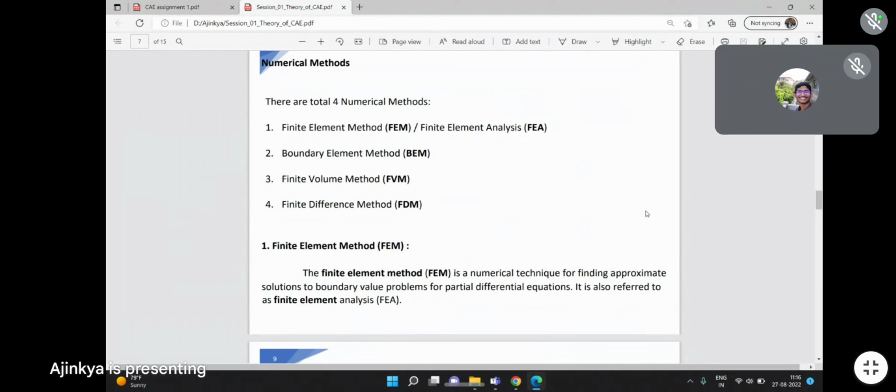What my equation of motion tells me, maybe I'll just write it for you. Force is equal to mass into acceleration, plus k into x, meaning my stiffness into my deflection, plus c into x dot, meaning whatever damping factor I have into my velocity. So m x double dot plus c x dot plus k x is the general formula for my equation of motion. From that, it is derived that force is equal to mass into acceleration. So from that formula only, all finite element analysis